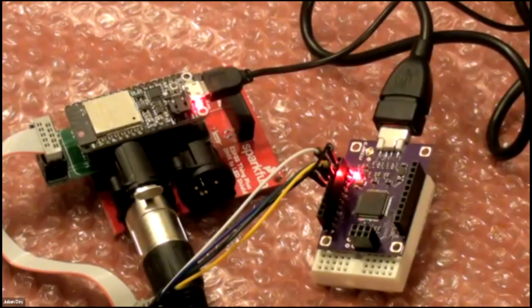I normally start poking around in the debugger, because that helps you understand the code. What's referencing this value? What does the call graph look like? These sorts of things you can generate statically. Again, mostly from a support perspective, I get thrown big chunks of code and told this doesn't work. JTAG gives you some clues as soon as you try to run it, but oftentimes it's a bit of detective work back in the debugger.